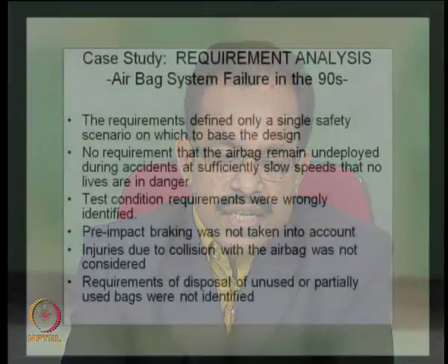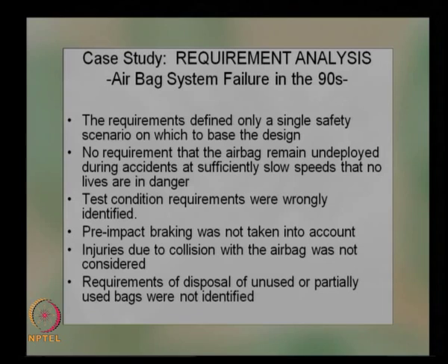The second one: no requirement that the airbag remain undeployed during accidents at sufficiently slow speeds that no lives are in danger. So this also was not envisaged. It was assumed that in any case where there is an accident, the airbag should deploy, but in most cases when the speed was sufficiently low, there was no need for the airbag to deploy, but since that was not envisaged, it actually led to failure of the airbag system.